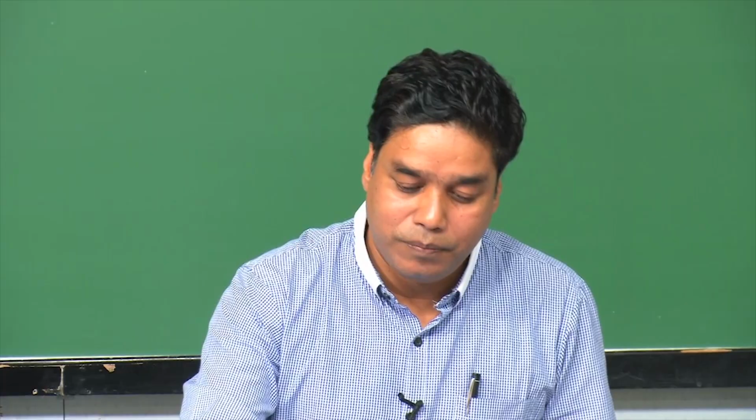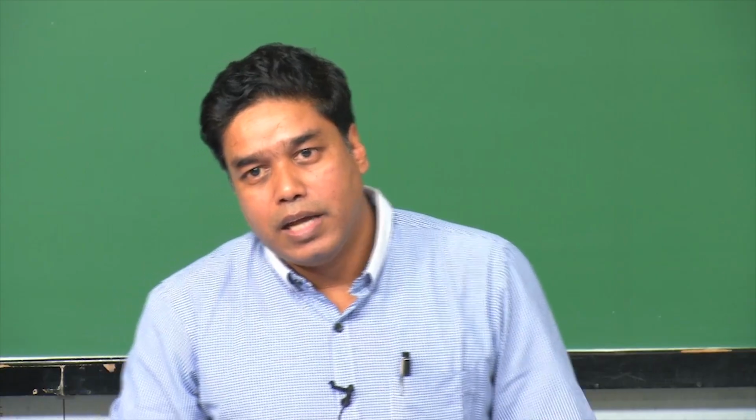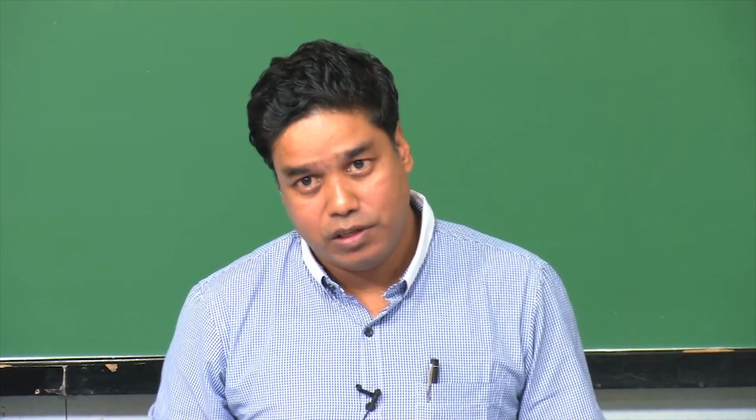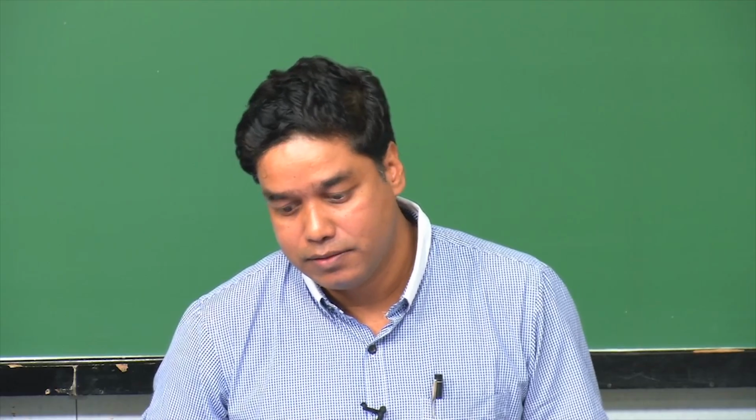So, for example, if you see that along this particular slot, maximum number of particles are being deposited or attracted, then you would know that this will be the direction of the magnetic field. Okay. So, this is also helpful in identifying the direction of the field, because that is also important in magnetic particle testing.